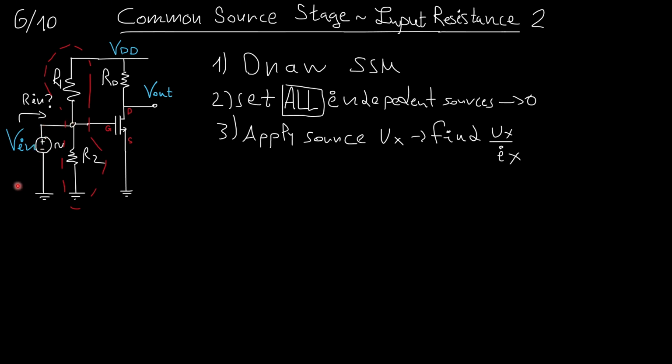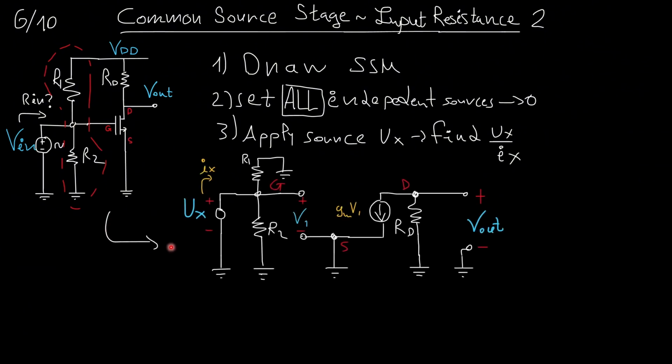All right, this is similar to whether we have a battery here and a voltage signal here. Again, I am to measure Rin, and in that case, this resistance will be connected to the ground, the AC ground. This resistance will be again connected to the AC ground, and I will connect a voltage of Vx here, and I measure the current Ix.